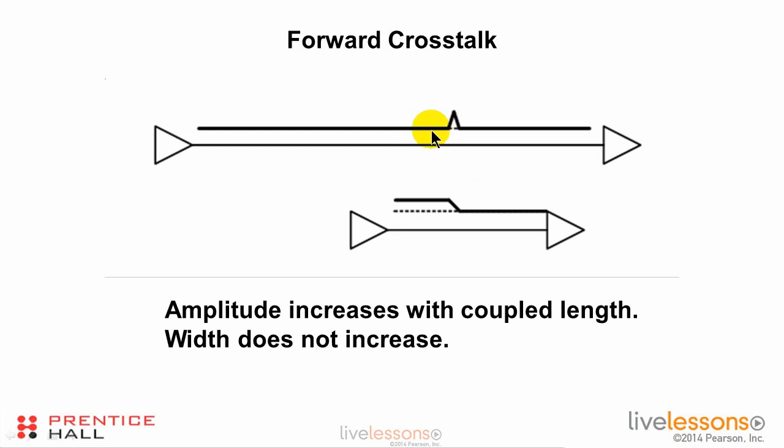But the signal that had coupled into that trace is also moving along at the same time and at the same speed. So they are moving together down these two traces, and the coupled signal reinforces the coupled signal from the increment before. And as we continue down the trace, we see that this continues to happen.